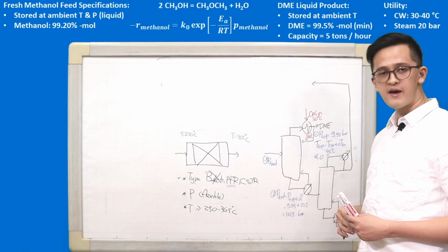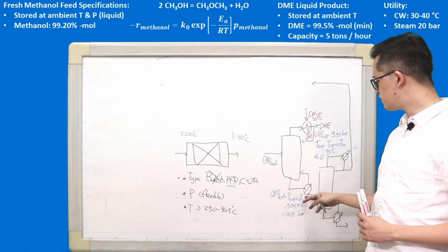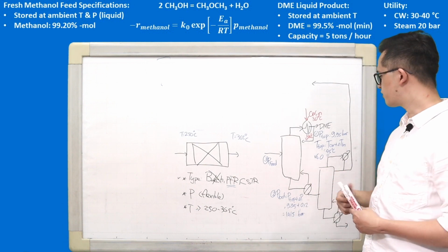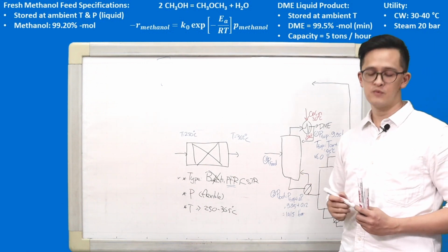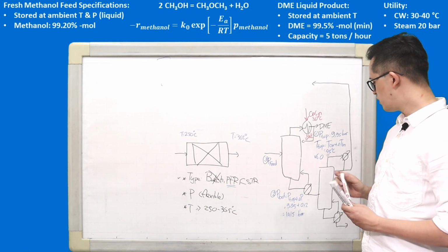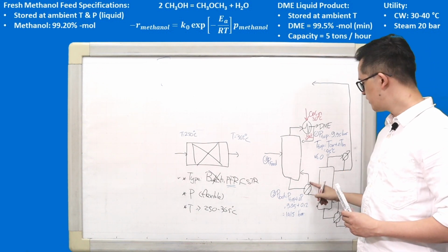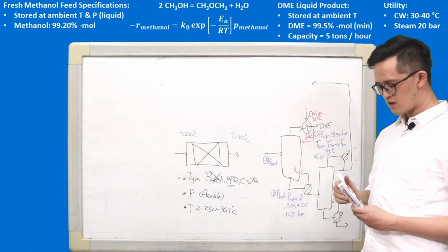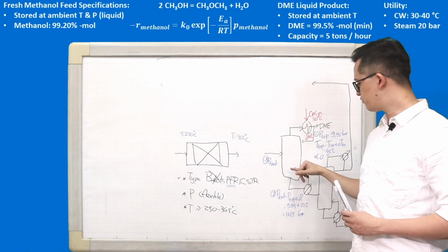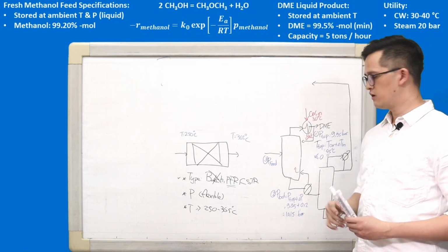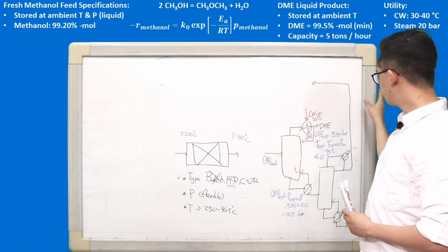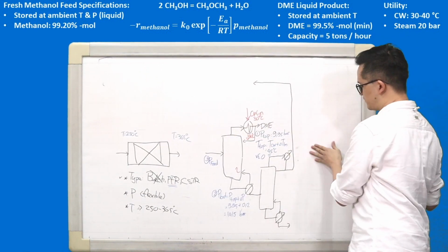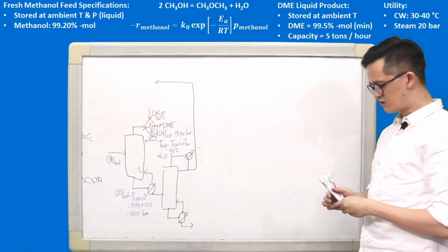You can answer that question by imagining what will be the pressure drop for the vapor when it enters the bottom of the column. Once you reboil the bottom stage, you get a vapor, it will go to the top, and what will be the restriction for those streams to go to the top? In order to make it easier for you to understand, I will make another diagram of a distillation column.